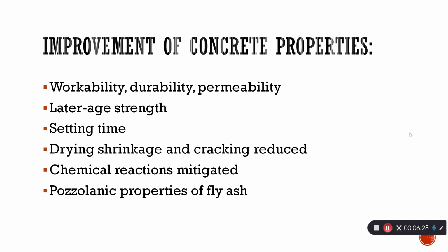The setting time of concrete being delayed when using fly ash is because of a reduced heat of hydration. This can be a beneficial application because a delayed setting time can prevent thermal cracking when using fly ash in a larger concrete structure. Drying shrinkage and cracking are improved and can be reduced when using fly ash because the amount of cement paste is reduced, which reduces its shrinkage potential, and the microstructure of the concrete is modified when adding fly ash. Fly ash improves and mitigates chemical reactions in concrete.